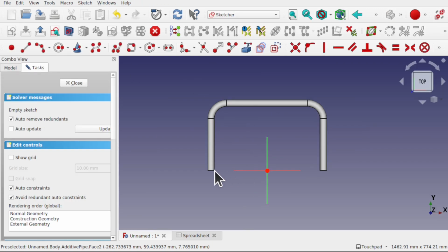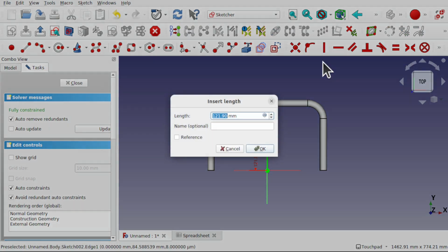Now we don't need to create a line that's going to go here. We want to keep it centered. Let's just place a single line centered in here. We're going to control this by length and placement. Let's hit escape, get the mouse pointer back, and set some length. If I come out to the length, we insert in length. Let's come to the formula editor.